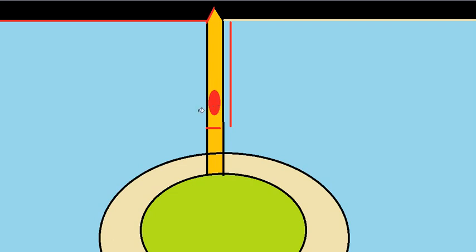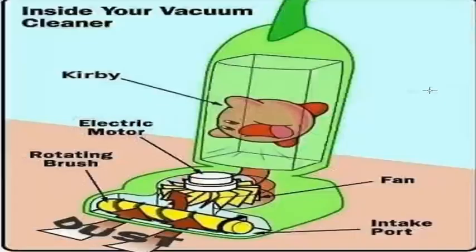So our basic requirements we can understand from here is we require suction here so that it can suck the fluid, and this device should give energy to the fluid so that it can lift itself to the surface. So we require two things from our downhole equipment. One is it should suck oil from the bottom, and another, it should provide sufficient energy to the fluid so the fluid can travel to the surface.